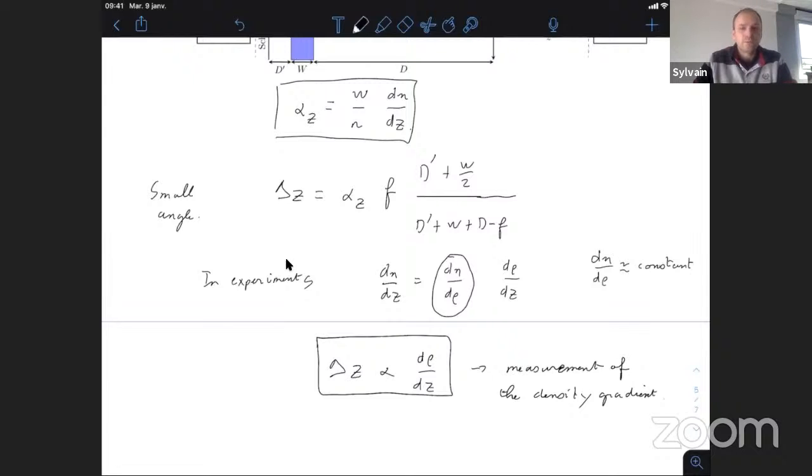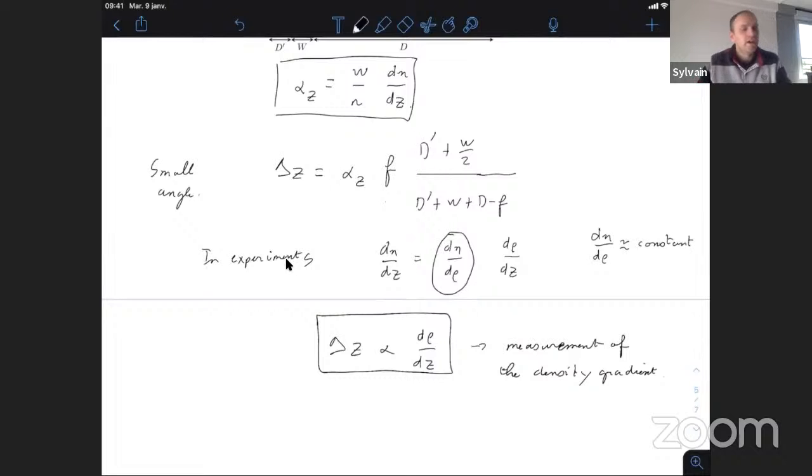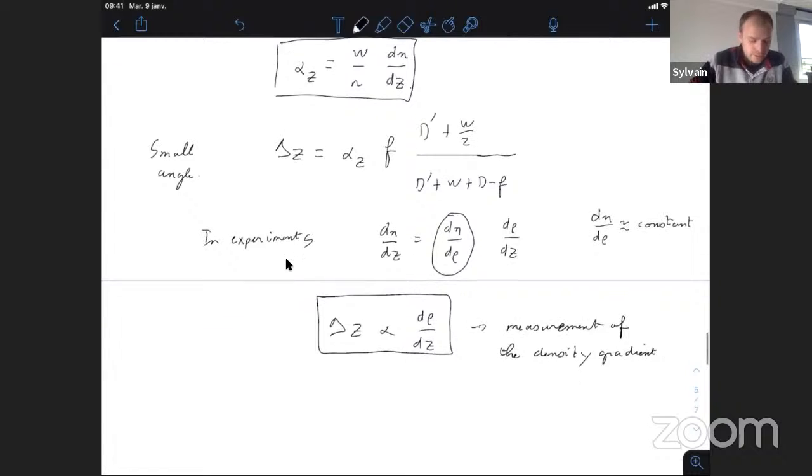That's why we always use random dots, and we use an algorithm to recognize a pattern that is randomly distributed, and this helps a lot for the resolution we can achieve. And we use exactly the same post-processing that we use in PIV. It's a multipass method by autocorrelation, and this helps reduce the errors and gives more accuracy.